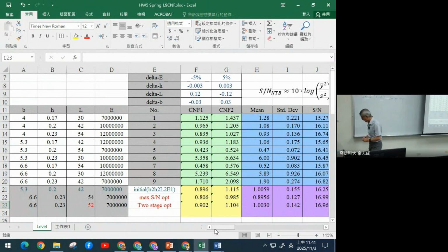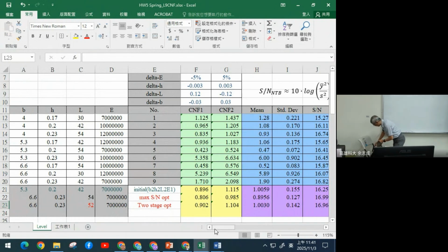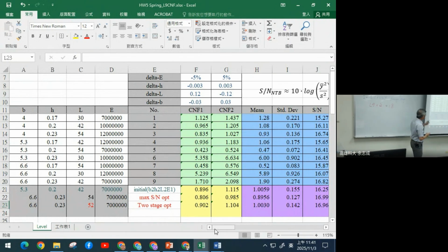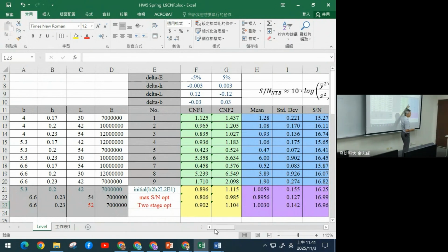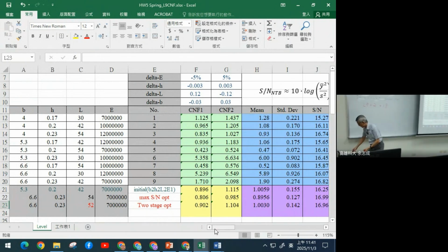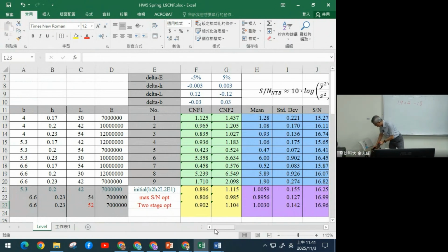In this design experiment, how many samples did you do? You pick L9 and multiply by 2, right? Since the compound noise factor, you choose 2 levels only. So there are only 18 samples. Only 18 samples. However, you still need to consider what? The sample you use to find out the direction of the noise factors, right?